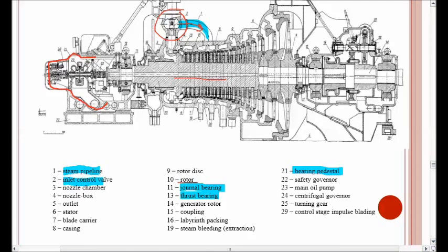That means the shaft of the turbine sits on a pedestal arrangement, a static arrangement that connects your turbine rotary shaft and the ground or the basement. Okay, this is a static body which has the whole turbine over it. Over the pedestal bearings, to assist the rotary motion, we have another bearing called a journal bearing.